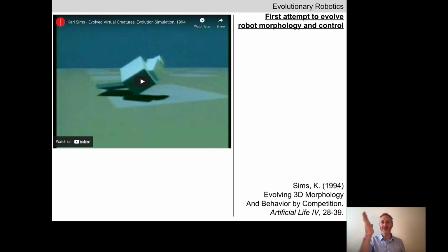On the other hand, as something is pushing through water, you can take more or less again that front face and compute a different force, which is how much force is being pushed in the opposite direction, the lift or the thrust at the point of the joint. So if this is a fin that is pushing backwards through the water, there is another force that you can add that pushes the joint of the fin forward, the propulsion that's provided to the main body of the fish or whatever it is that's swimming. It's actually not too difficult.